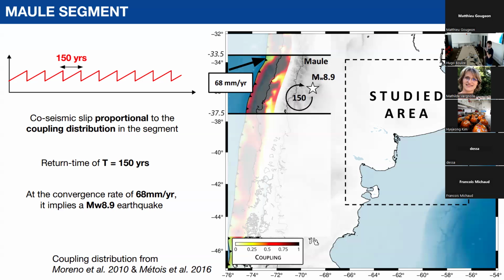The other thing I am exploring in northern Chile is the problem of the sliver, this third plate hypothesis that I presented at the beginning. There are people discussing whether the Liquiñe-Ofqui fault played a role during the Valdivia earthquake. So you have the problem of the sliver in the north, but maybe adding viscoelasticity in our models will be able to reconcile these two-plate or three-plate hypotheses.